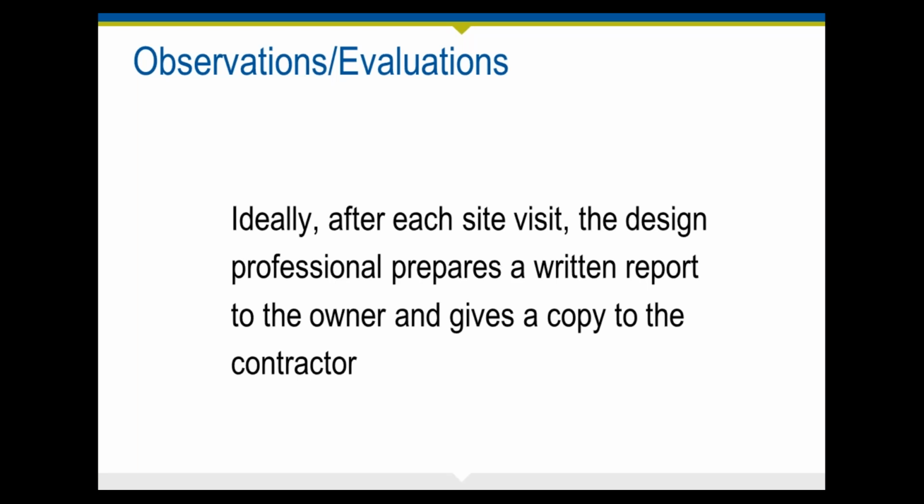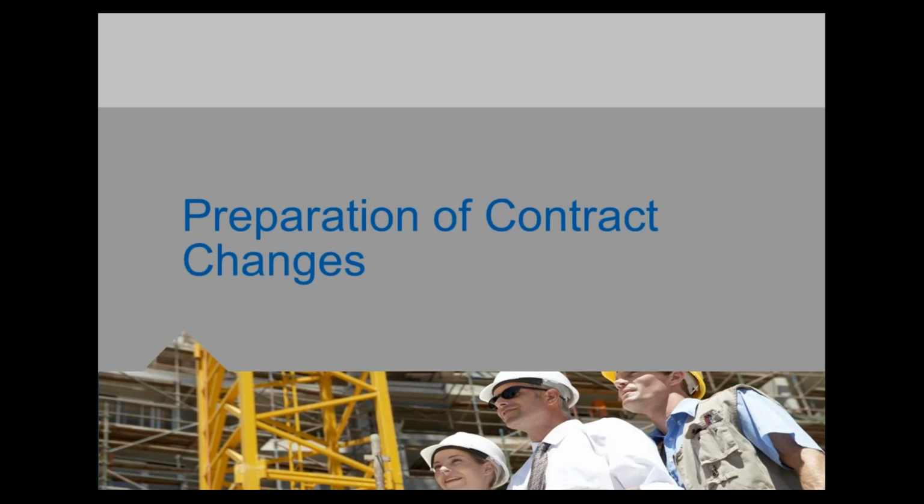So one thing that we suggest is that after each site visit, you prepare a written report and say, okay, we were on site, these are the activities we saw, these are the things that were going on. Whatever it is, oftentimes there may be a form that your firm has developed. In other words, if you are on site, it's always a good idea, at least from my observation, to document that you were on site, what you saw, and provide it to others, so that if there's any question about what exactly was going on that day when you were on site, then you have some documentation to help provide you with an answer for any questions or issues that may come up.